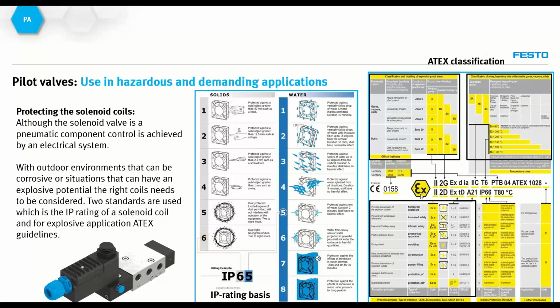But also a common technology is increased safety or intrinsically safe systems. Again, this is identified with the blue cable glands and blue cabling, where the power of the supply voltage and current is so low that even if the wires short-circuit, they are not creating a spark strong enough to ignite the environment in which it's operating.